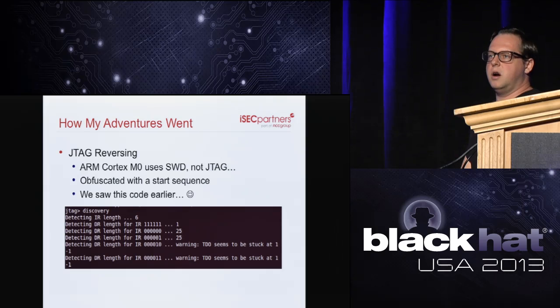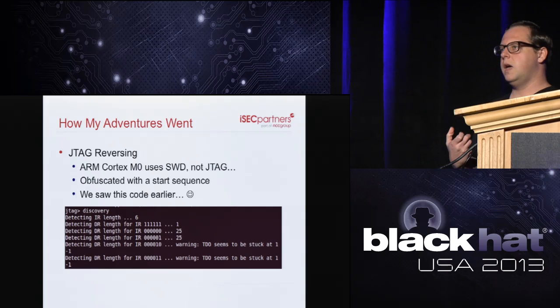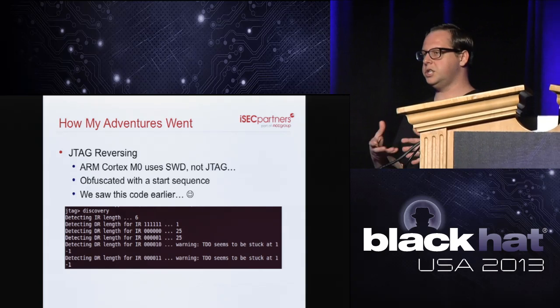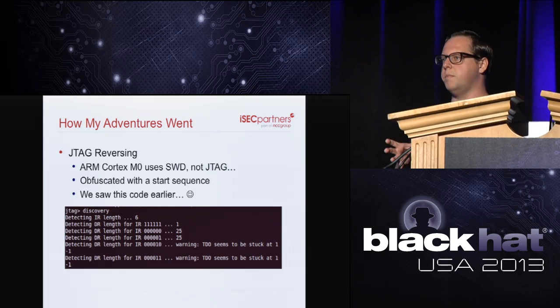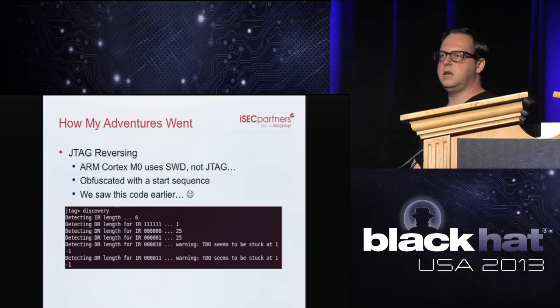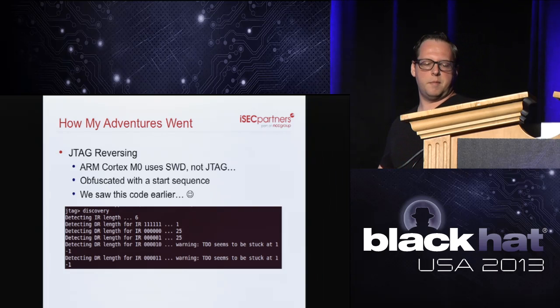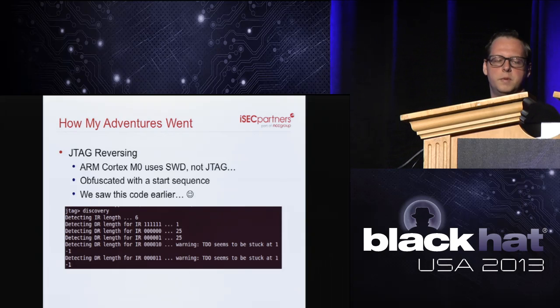However, those lines are pulled to ground, so it's not using SWD to do any testing or flashing. It looks like all of these pins that are hooked up are going to port 3. A port on a chip is basically a collection of pins that usually serve one purpose. So they're all going to port 3, which leads me to believe that port 3 has been reconfigured to do a custom JTAG implementation on the ARM.